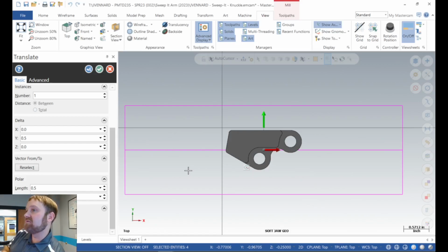So when we cut this soft jaw, we're just going to take our shortest parallel, stand it up in the bed of the vise, and close the vise on that parallel. That's going to hold that 1/8 inch gap while we cut the pocket. So what I need you to do here is add to the Y, we're going to add a 1/16. Why a 1/16?